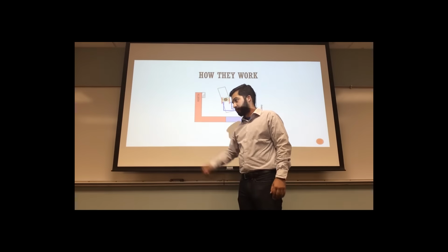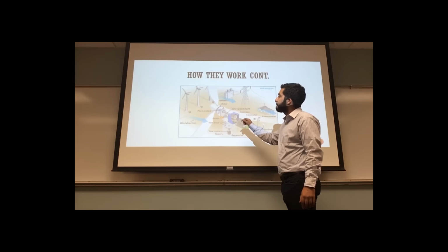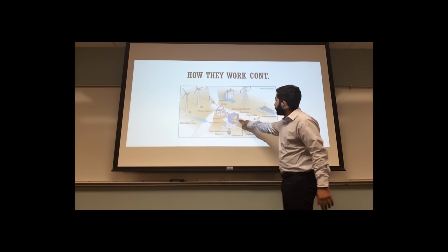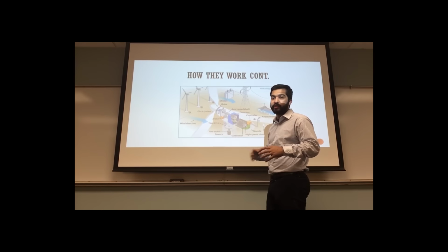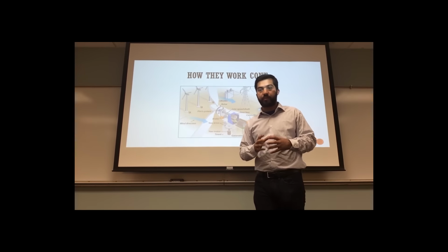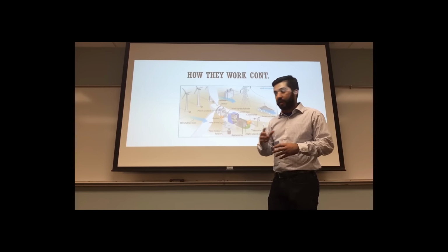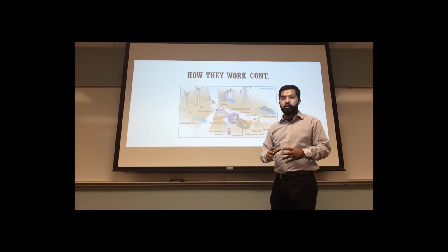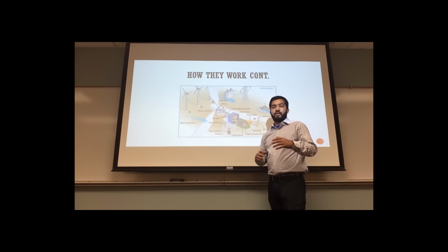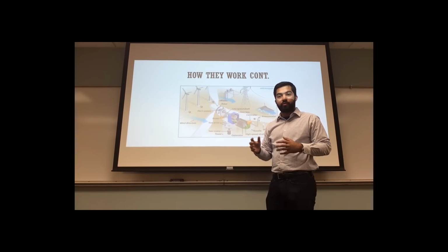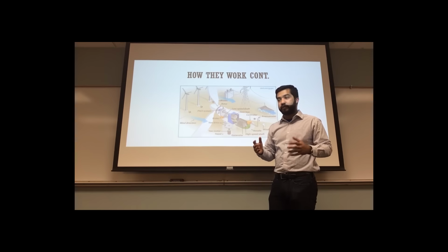In a wind turbine, this is how it looks. The generator will be right here in the back. So the generator, in order to produce the correct frequency to connect to the grid, needs to spin at a certain speed. How is that achieved? We have a gearbox. The gearbox spins the shaft from the input to the output at the right RPM, or revolutions per minute. So a 4-pole rotor spinning at 1800 RPM will produce 60 hertz. 60 hertz is the standard for the US. For European nations, it's 50 hertz.